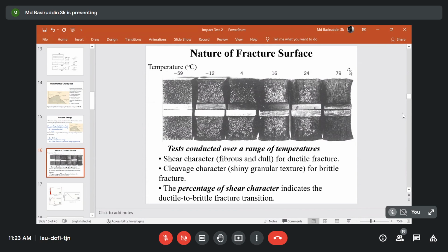If plastic deformation happens, the cross-sectional shape change will happen, and that will be reflected in the fracture macrograph. But if the material fails under the elastic region, there will be no change in the fracture surface or the cross section of the specimen.